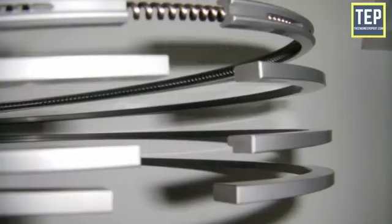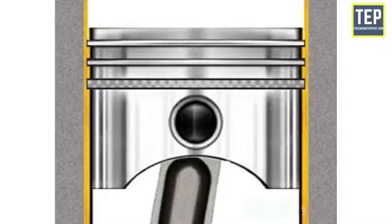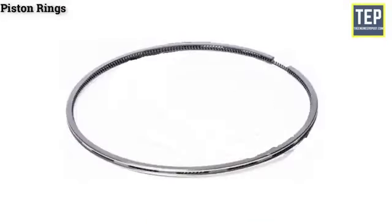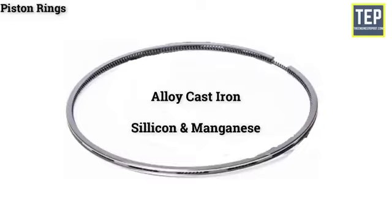Piston rings. The piston rings are fitted into the grooves of the piston to maintain a good seal between the piston and the cylinder wall. The function of piston rings is to form a seal to prevent high-pressure gases from the combustion chamber from entering the crankcase. The material generally used for piston rings is fine-grained alloy cast iron containing silicon and manganese. It has good heat and wear-resisting qualities.